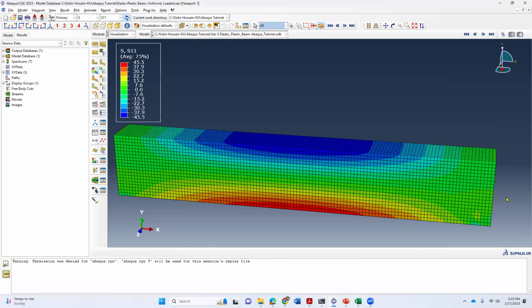That's 12 inch by 20 inch. It's still a rectangular section that can carry a lot of force, right? But I overloaded it basically. But I want you to see the stress evolution. So you can see till now the flexural compressive stress at top and flexural tensile stress at the bottom are exactly equal. Keep an eye on the stress value and also the contour movement.